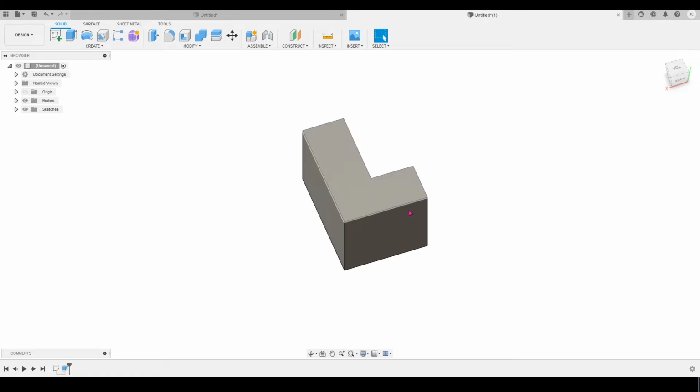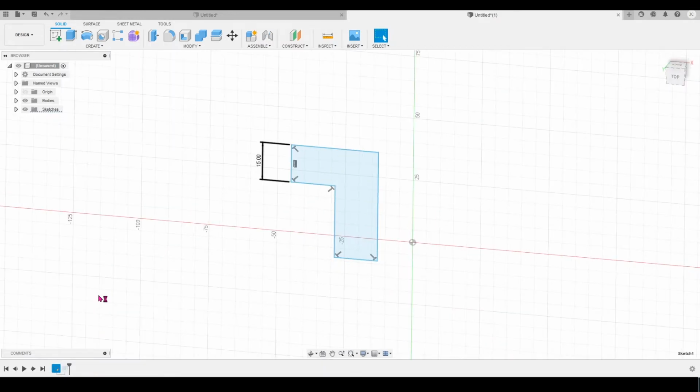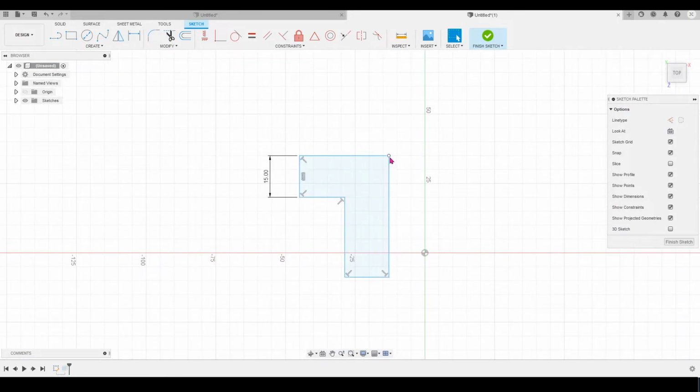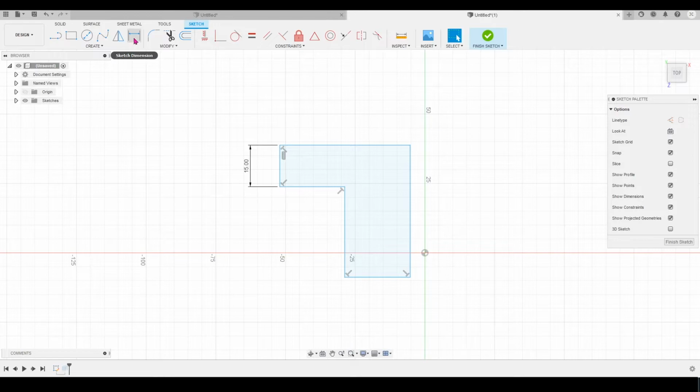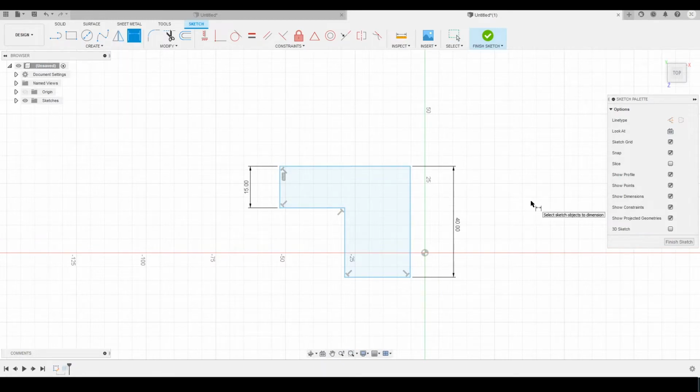Now if you want to modify the shape itself, you go to the sketch in the history on the bottom left, right click, and edit sketch. Now when you have a sketch, for the most part you can drag these points or drag the lines. You can change these dimensions. Now you might be wondering, what if I want this line here to be a certain distance? So now we have this tool on the top left called sketch dimensions. This only works for sketches. So we click on that, and then we click on the line, and basically it tells you what length that line is, but we can also change it. Right now it's 47.6, and let's just say we want it to be 40. You click enter, and it'll shrink it down for us.